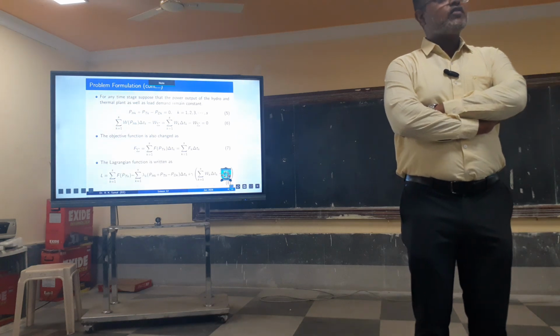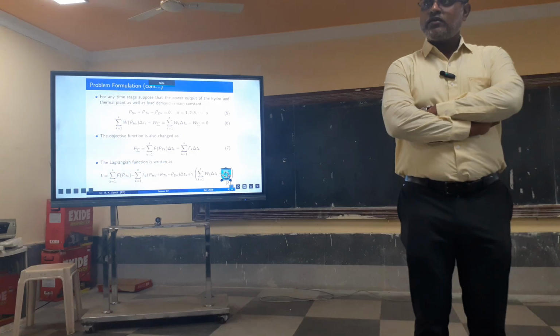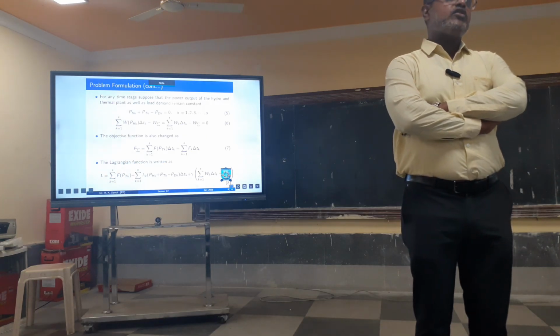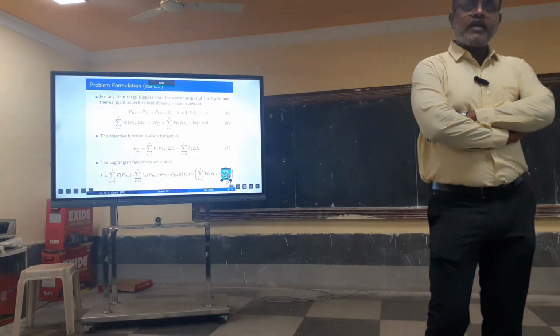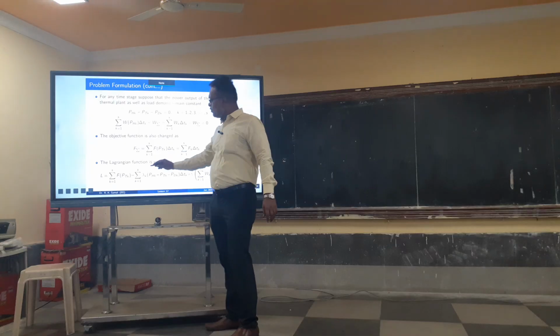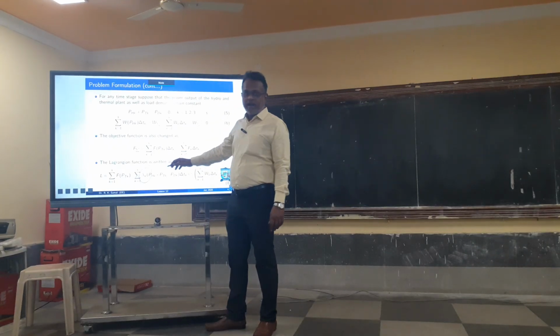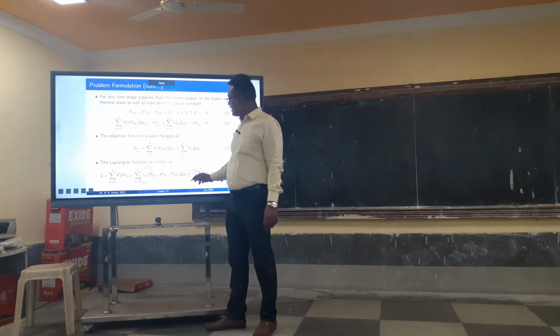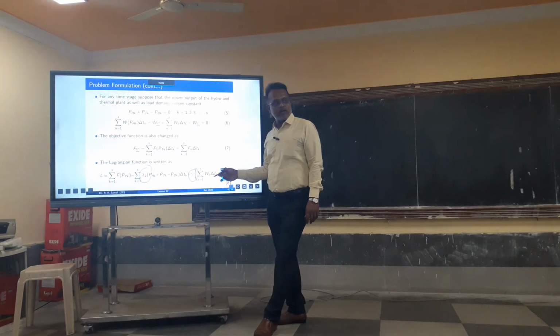Now here there are two different constraints, two equality constraints. One equality constraint with respect to power balance and the other equality constraint with respect to the water availability. So therefore in this case we have two sets of Lagrange multipliers. One is known as lambda k for the demand equality or demand balance, and gamma for the water availability.